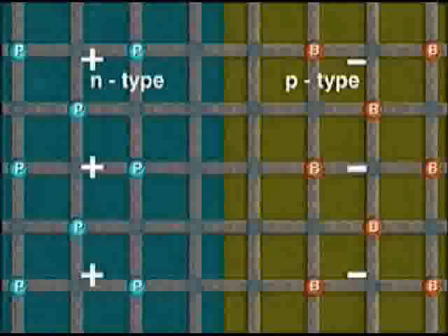This time, however, before the hole and the electron can recombine to emit a photon, they are separated by the electric field created by the p-n junction. The negative electrons move to the positive region, and the positive holes migrate to the negative region. Therefore, by separating the electrons from the holes, we have prevented their spontaneous recombination and loss of their excitation energy. Now we have all of the pieces required to construct a solar cell.